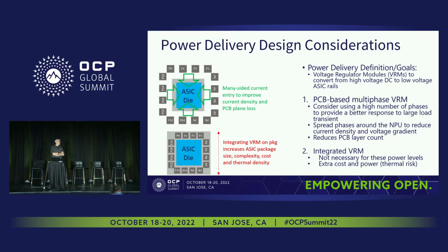The other side is, on the thermal side, we're also combating large thermal density hotspots within the box, and moving the voltage regulators onto the package, where typically there's about 10% loss in those regulators, would increase the thermal density of what's on your package by 10%. So this is an interesting technology, but this goes in the only-if-it's-necessary bucket for us. For us in our work on 50 terabit systems, this technology is not necessary. And you'll see, while there have been some discussions on the CPU side, that it is not really needed outside of the CPU realm.